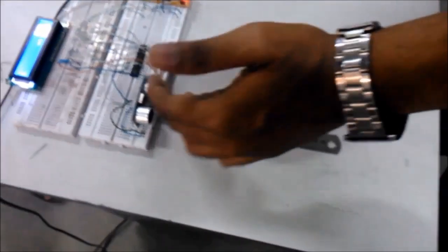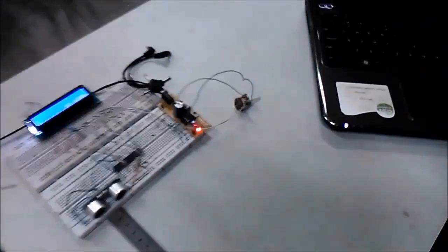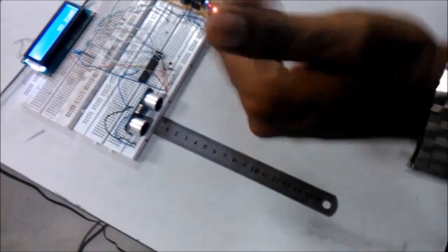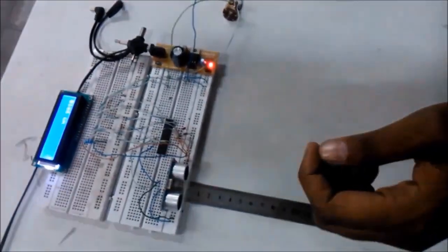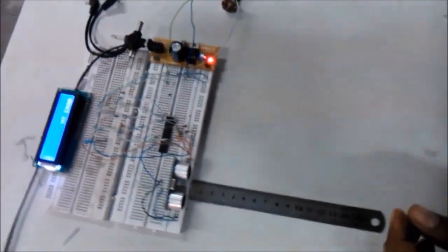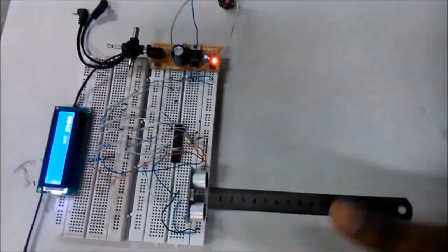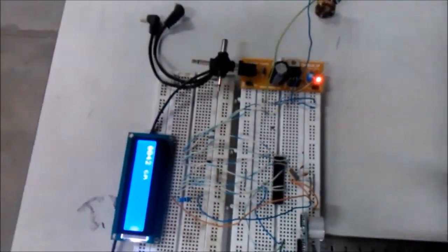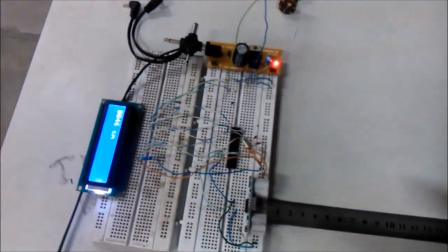A short ultrasonic pulse is transmitted at time 0 and reflected by an object. The sensor then receives this signal and converts it into an electrical signal. The next pulse can be transmitted when the echo has faded away. This time period is called the cycle period. The recommended cycle period should be no less than 50 milliseconds.